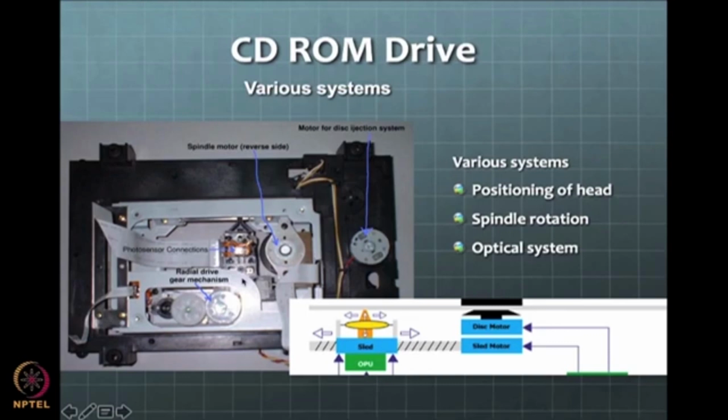In this sliding, how are people making this slider? Since there is a slider, the friction will be there. No one can have a system with friction, but we saw that with friction you cannot position below 50 microns, for example. So how do you position to the nanometer range? What additional systems will they have? There are some systems very close to the lens which are doing this positioning. We'll see all the details in the classes to come.